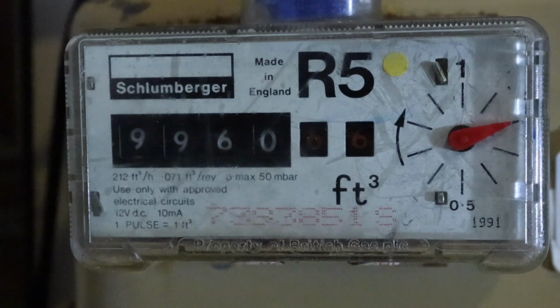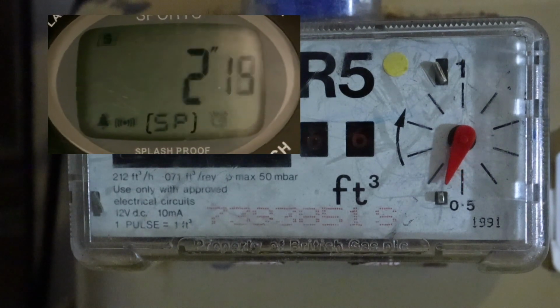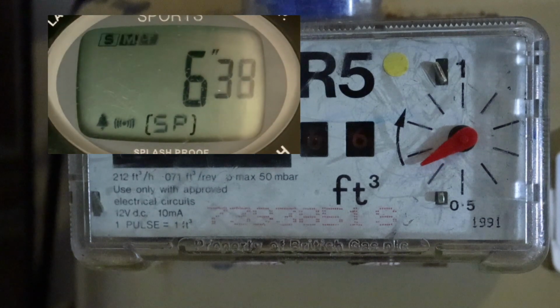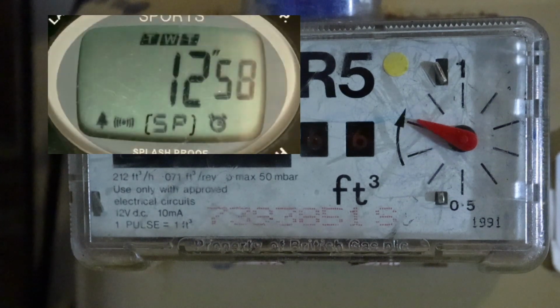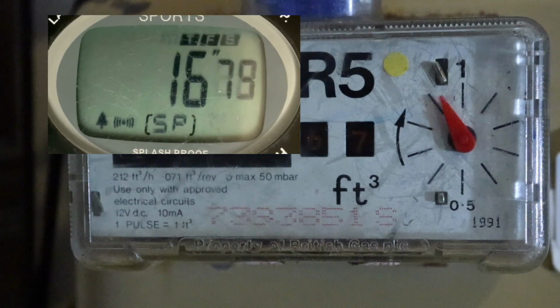Now I've got the tap running. I'm just going to wait till the finger goes all the way down to the bottom, and then I'm going to start my stopwatch and I'm going to time how long it takes to do one full revolution, and we're off. So the reason why I wait till it gets to a full figure is because it's easier to judge then. So I always do it at 1/2 or 0:00. It depends what you're gas rating really, but I'm gas rating the boiler.